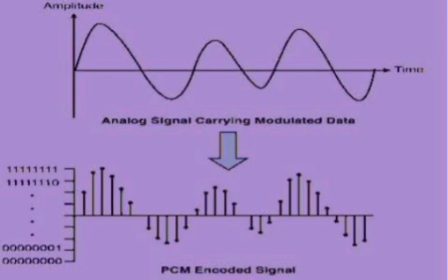Noise in digital communication: for better SNR a matched filter is used, whose impulse response h of t equals s conjugate of TB minus t, where conjugate represents the complex conjugate. TB means bit duration, and s of t means the input signal to the filter. Probability of error PE equals Q of root over differential energy squared by 4 into noise spectral density. PE equals Q into root over ED by 2 N naught, where ED equals the integration over TB of S1 of t minus S2 of t, whole squared, dt, where N naught by 2 is the two-sided noise power spectral density.